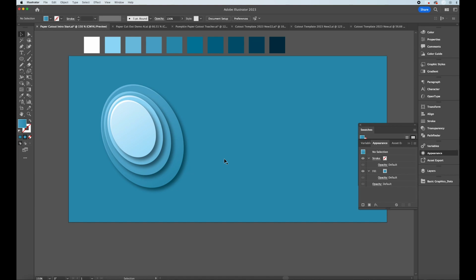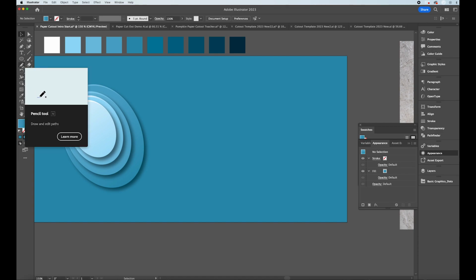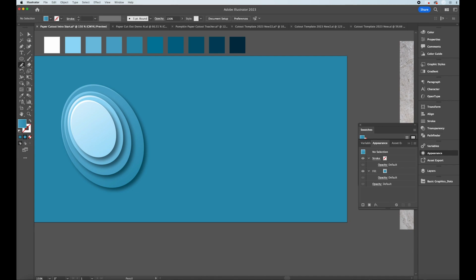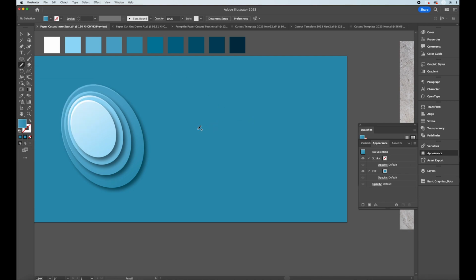Now we have this right side to really understand how we can now create depth and do cutouts within sections. If I want to create depth over on these pieces to the right side, where we can get into a little bit more customization, I'm going to go over to the pencil tool. Pencil tool, left side navigation. If double rows, 6th icon down. I'm going to use the pencil tool to click and drag to draw out a more free-form shape.